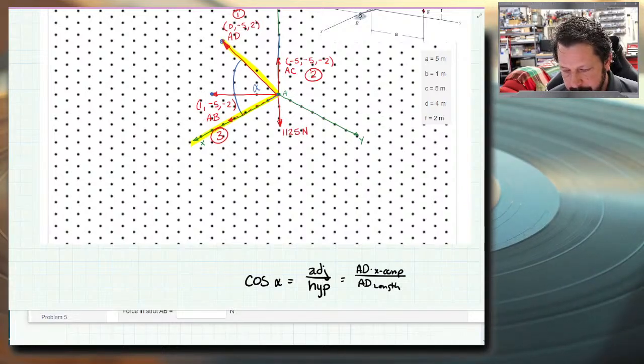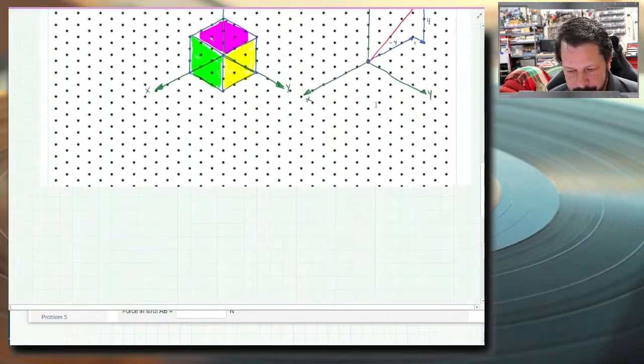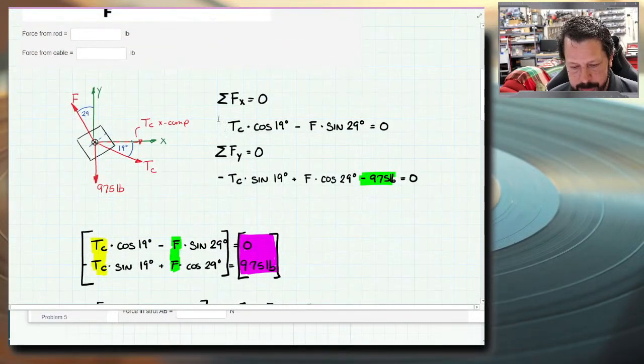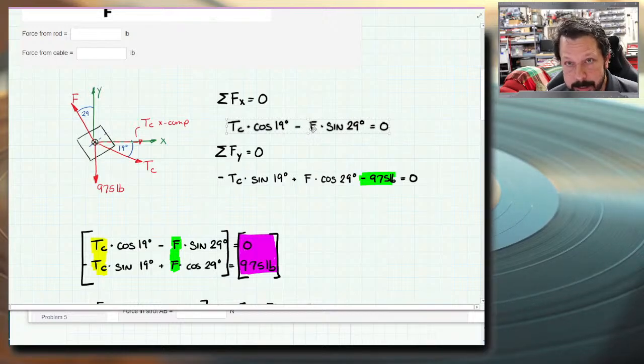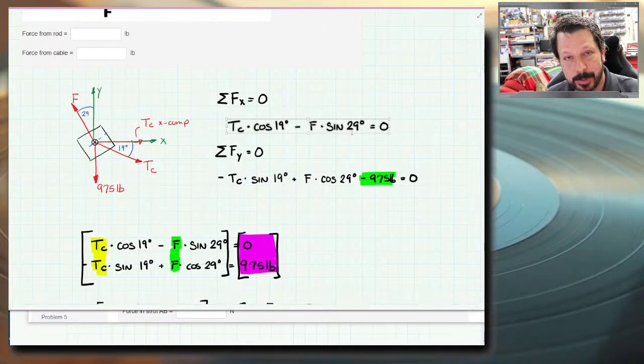And if I have that cosine of alpha, remember, what I ultimately am trying to do is write equations like this: T_AD times the cosine of alpha minus T_AB times the cosine of its alpha or beta or whatever we want to call it. We won't have enough variables to name each one of these angles, right? Because each component, X, Y, and Z, gets its own angle between that axis and the force component, and there are 3 force components, so there are 9 different angles.